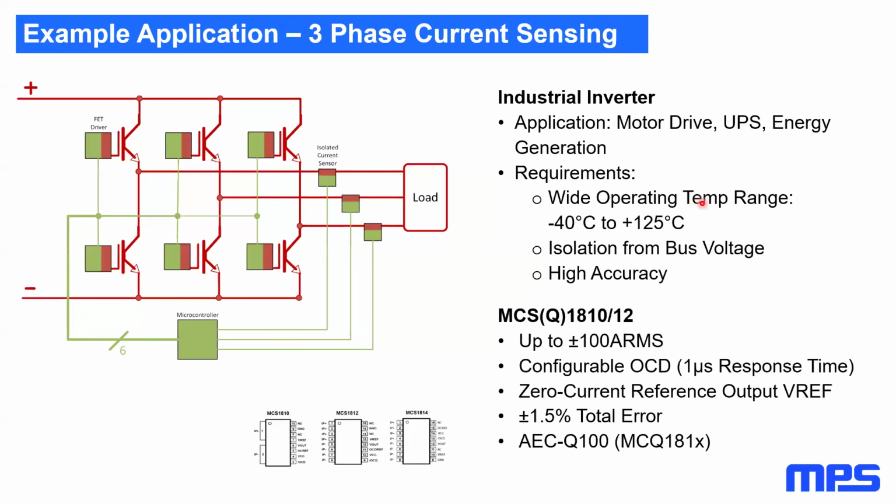In current sensing, it is quite the same, except that instead of a permanent magnet, normally we're seeing interference from other phases. So here's a very typical current sense application. We've got a high voltage bus and 6 switches. So we've got our 3 phases here. I think I have these as IGBTs. They could be MOSFETs. Anymore, I think they're like GaN FETs a lot of the time. In any case, each phase has an isolated current sensor put on there.